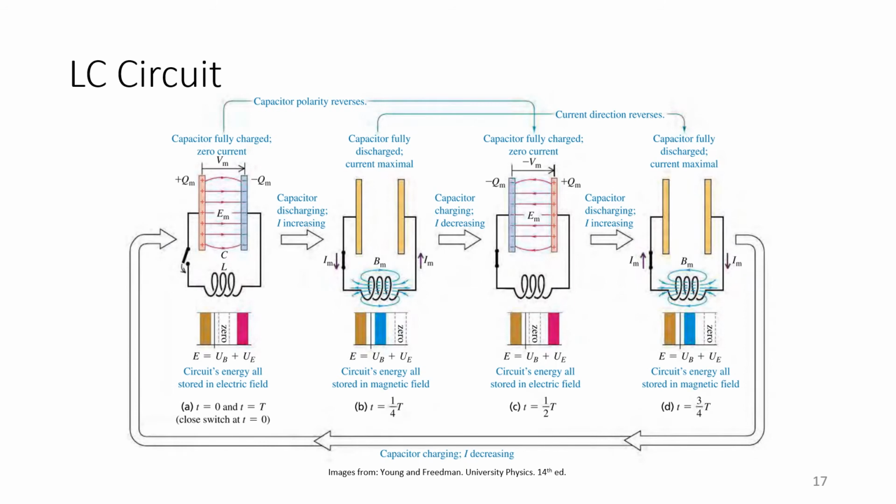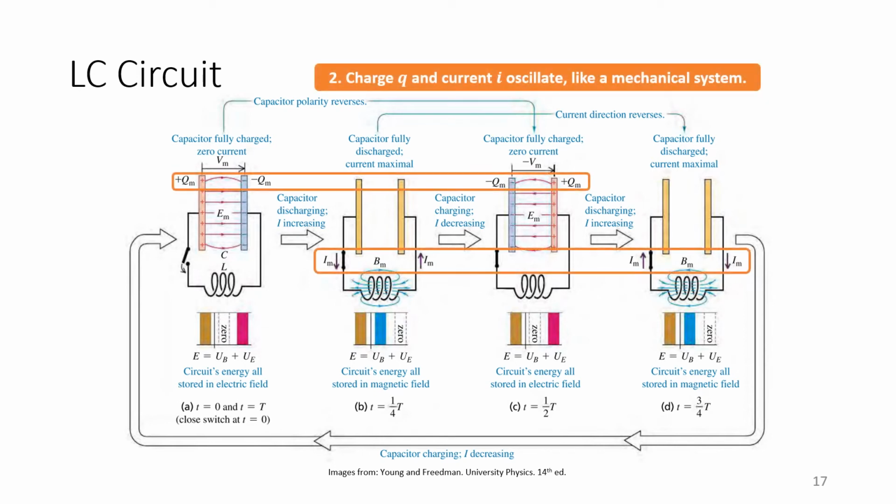This slide provides a larger picture of the LC circuit cycle. What's not as obvious from the previous slide is that values of charge Q and current I oscillate between phases. At max Q, the current, or the change of Q, is 0. At max current, the total charge is 0. This interplay between variables is also something that's been encountered in mechanical systems in Physics 71.